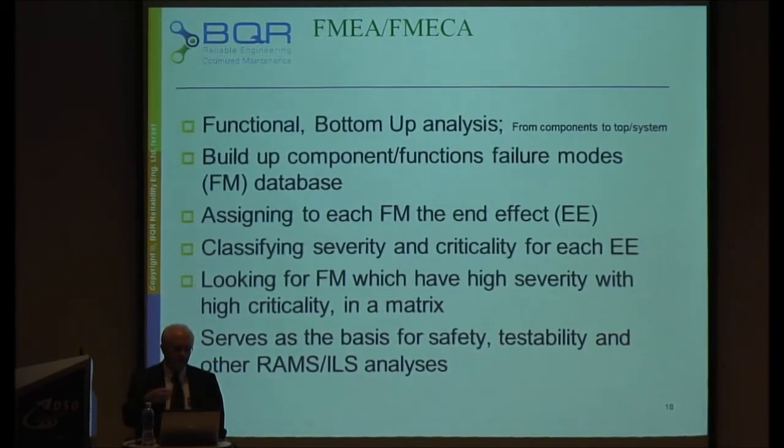For example, a resistor, it can be short or open. If it's a mechanical component, let's say like a bearing, one of the failure modes can be that it starts to go heavily, not smoothly, loose. So you need to define what are the failure modes of the component.